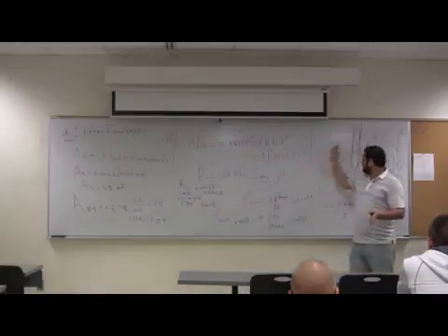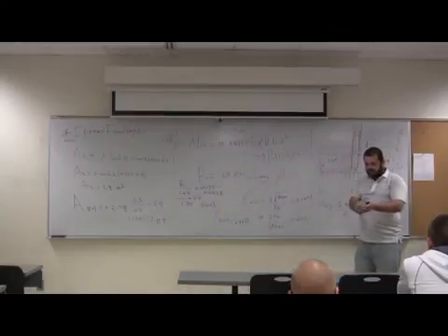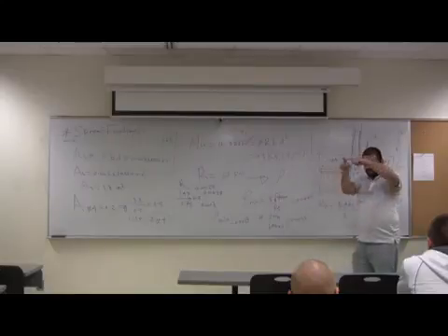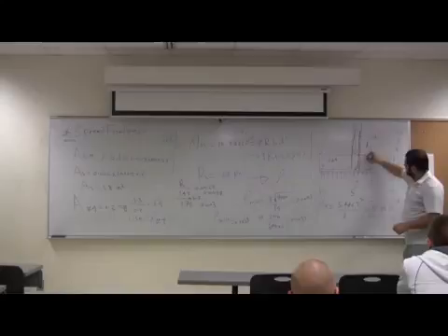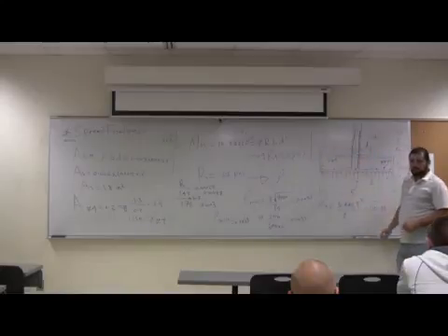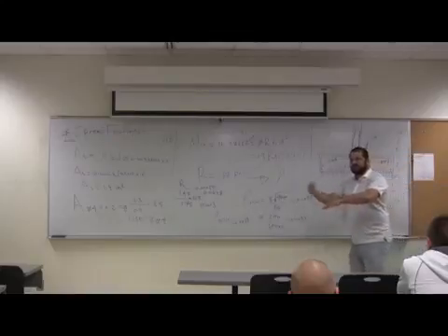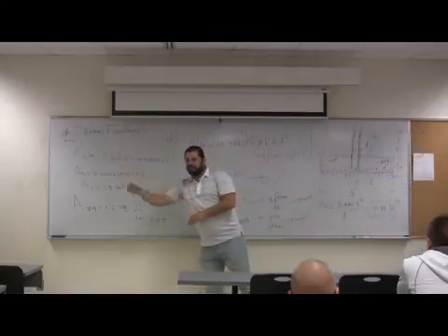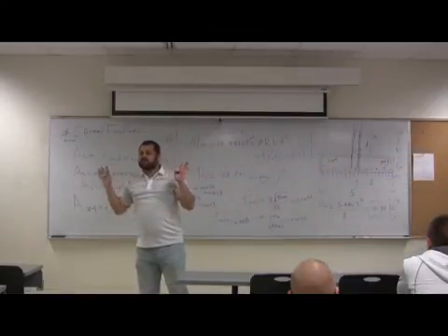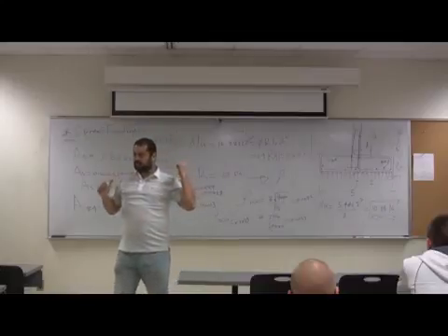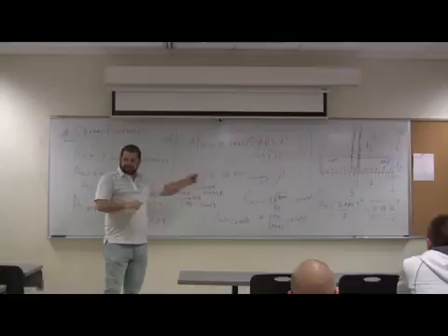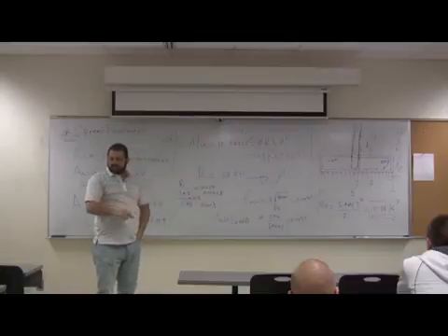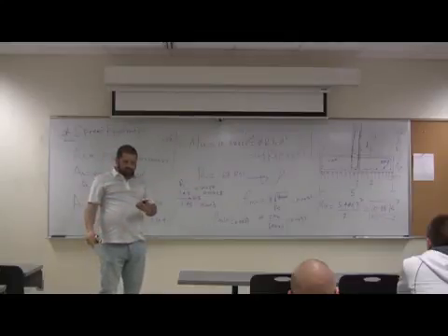You say to tie this reinforcement here, we take it and make it a closed rectangle. So they tie the bars here like that. They skip the second, third, or whatever, then they go with the next one. It's for constructability, not needed for design. Good? That's the design of the wall footing. Any questions on this? So you know how to design a wall footing now?